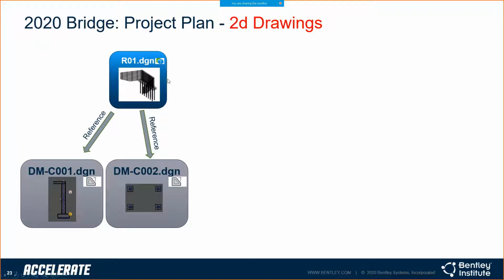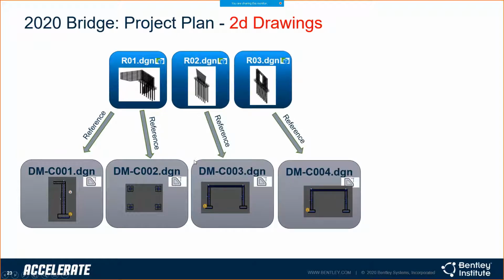And then from that, start using the section callout tool and generate drawing models. From this detail right here, you're probably going to have a lot of different drawing models to show various aspects of this. You're going to show it in a plan view. You're going to see it in an elevation view. You might want to see the footing only in a plan view. You may do separate things for these walls if they're different somehow. So each of those would have their own drawing models.